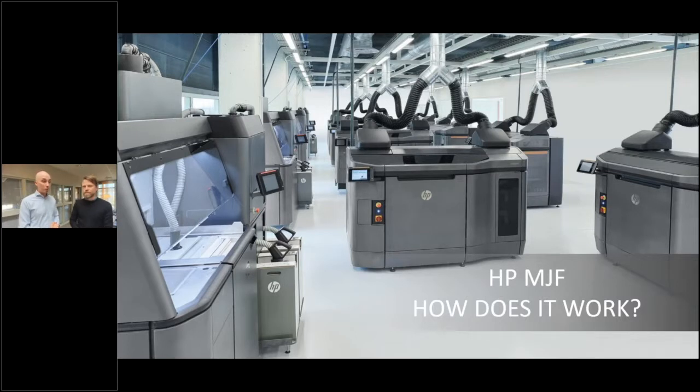It's called MULTIJET fusion. Basically what it is, in short, is that you have a powder bed that's heated up. Then you apply ink agents on top of it to create the geometry, and you apply extra heat to fuse the powder together. Then you take the parts out of the build chamber, you vacuum it, and then you sandblast it. So this has been a huge hit since it launched a couple of years ago.